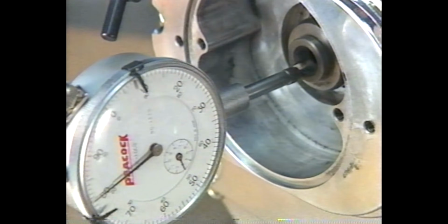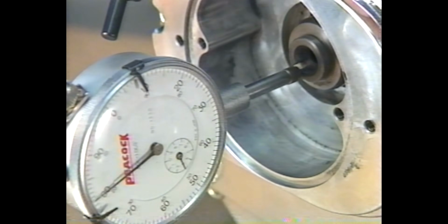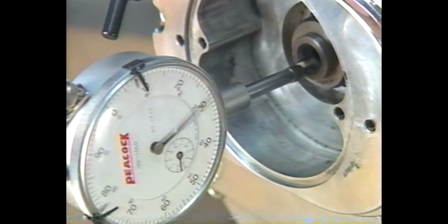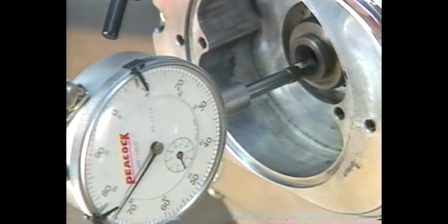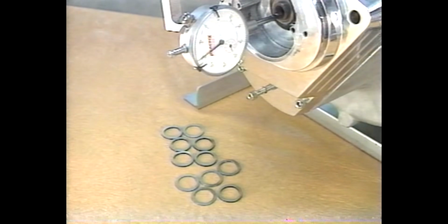A camshaft must have some end play, and the minimum end play we have found to work is 5 thousandths of an inch. The factory allows up to 50 thousandths maximum end play for stock Evolution engines. For more detailed information, please refer to the camshaft installation sections in the Evolution motor and Shovelhead motor video manuals. We prefer the end play in our camshafts to be about 10 thousandths of an inch, or 1/4 millimeter.